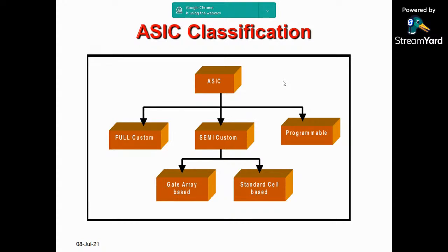But performance, which is better, is full custom. Why? You are customizing each and everything. Now I'm going to talk about the integrated circuit. What kind of material do I want to use? Whether I want to go for silicon, germanium, or hybrid compound semiconductors. Then what methodology, the number of layers, the placement, orientation of transistors, everything is in my hand. Semi-custom, you take help from a tool.